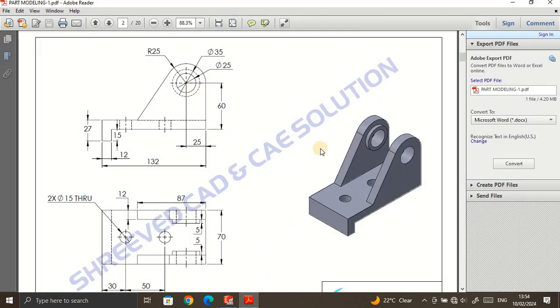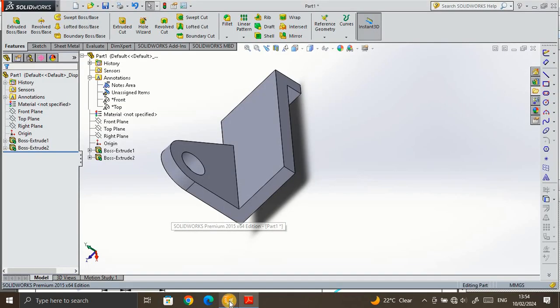This ring has a diameter of 35 mm. In front view we can see the diameter 35 and extended from the vertical surface 5 mm. This is a 5 mm extended portion with the internal hole also 25 mm. So for this we need to create two circles again, with 25 mm diameter and 35 mm diameter. So the ring will have a total width of 5 mm. We can extrude through this command. Extrude. We can use the extrude command.